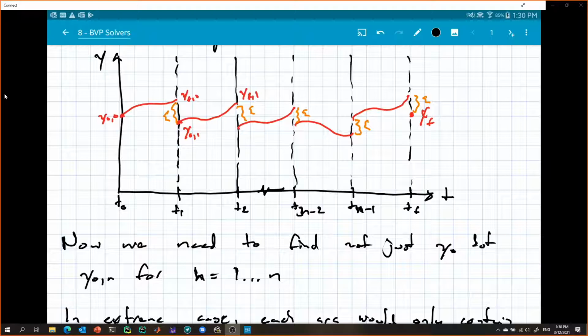What the multiple shooting method does in Beluga is it actually interpolates. It used to not interpolate, it used to just pick points, but now it interpolates for the number of arcs. So say you have 4 arcs, it will run a cubic spline interpolation to find the estimated values at T1, T2, T3, and then use those as guesses for T1, T2, and T3.